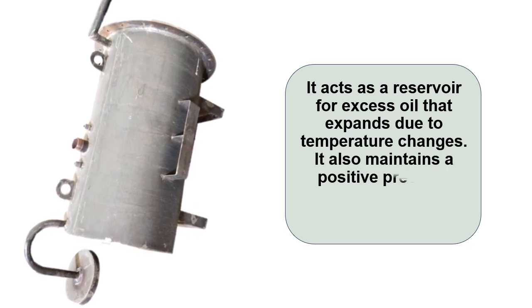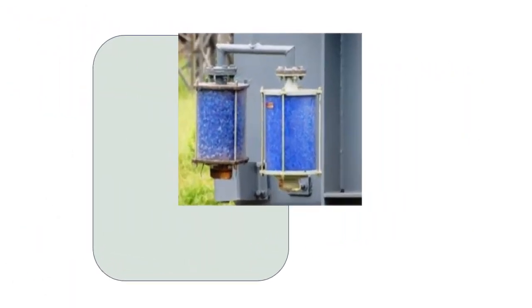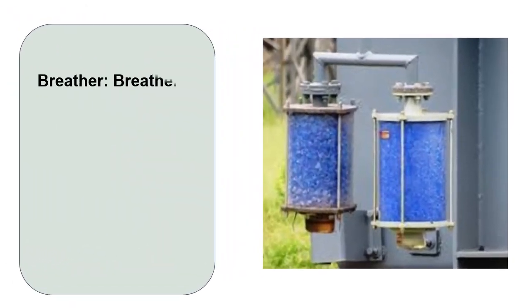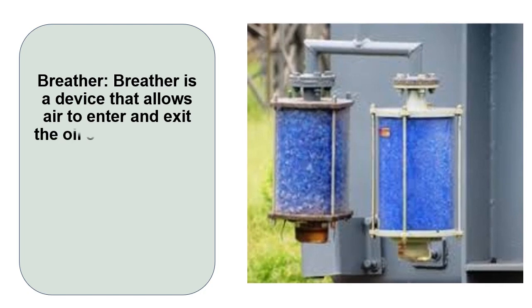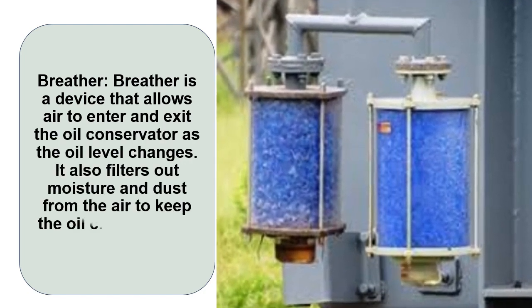Breather. Breather is a device that allows air to enter and exit the oil conservator as the oil level changes. It also filters out moisture and dust from the air to keep the oil clean and dry.